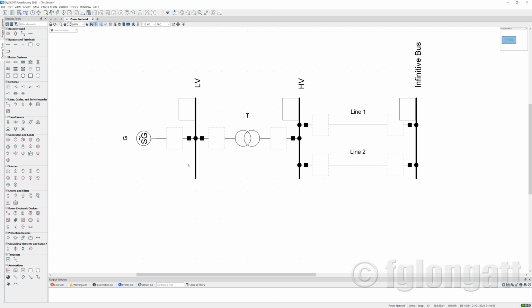What I'm trying to say is the external grid is a concept that we use to create a model of a large portion of the electrical power system, but keeping some elements regarding that very large network, okay? For instance, for electromechanical processes, for that external grid, there is a possibility of including, for instance, inertia, okay? It's not a good idea to use the external grid as a model for the infinity busbar, okay?